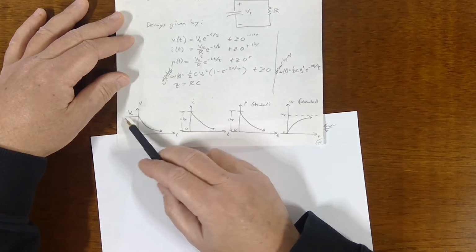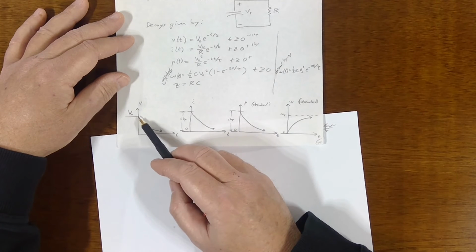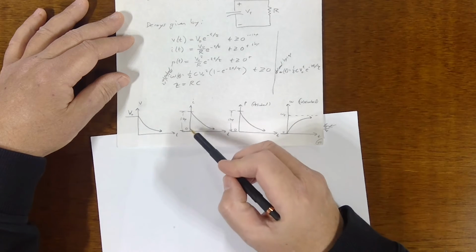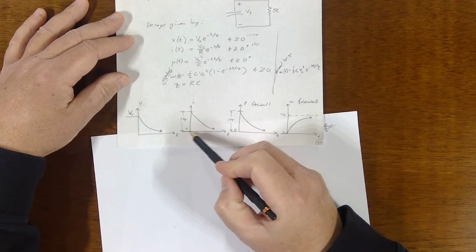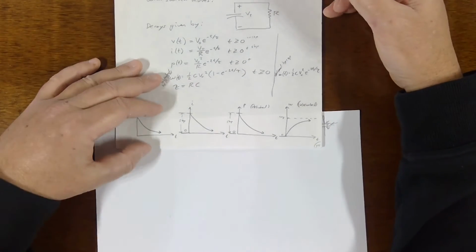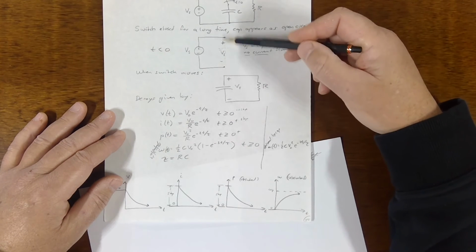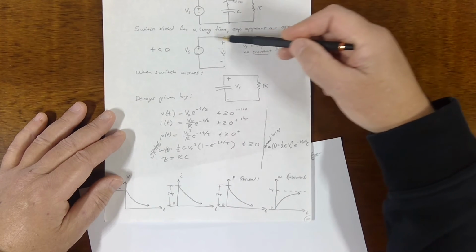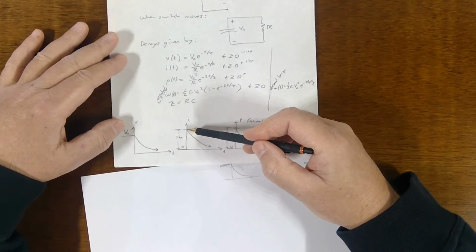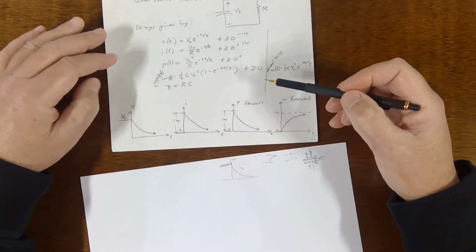And this is the voltage signal. It's steady state for t less than 0. And then we throw the switch at 0 and it decays like this. I is 0 before the switch is thrown, because there is a constant voltage across the cap at steady state. The current will be 0 for a constant voltage in a cap. But then you throw the switch and I will jump up to this value and then start decaying.